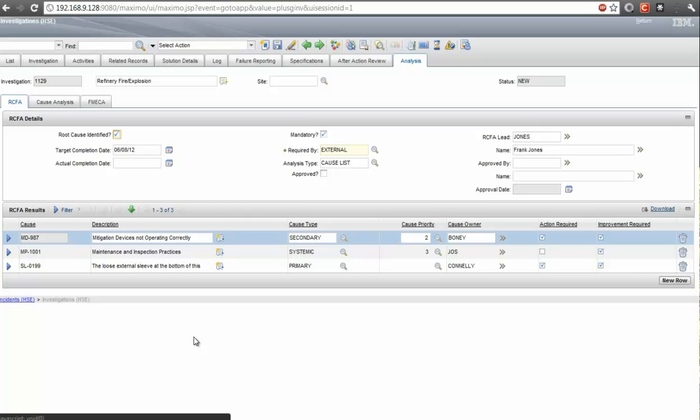The chain was actually off the sprocket, so they had to take a little more time to go get a ladder to reinstall that chain. When they got the chain installed, they went to operate it, and it was seized up. There was no maintenance policy to actually operate that valve, so the valve itself had seized up. So they actually had to isolate downstream, obviously resulting in more gas burning off, temperature increasing, and the residual damage had increased.